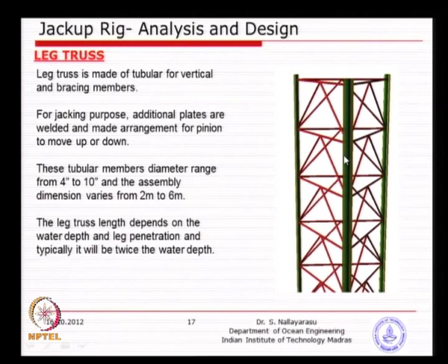and typical sizes of this varies depending on the size of the jackup, 2 meter, 3 meter, as much as one of the largest jackup 6 meters. So, almost like half the size of this room, so the leg size. Tubular members is not going to be very large because you are using a lattice tower. So, you will see that 2 inches, 3 inches up to maximum 10 inches like 300 mm diameter.